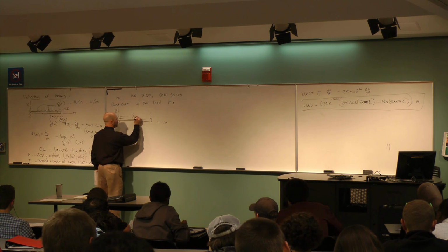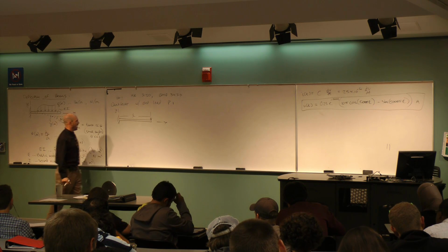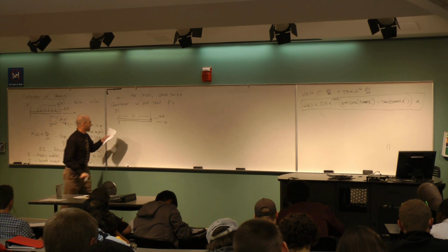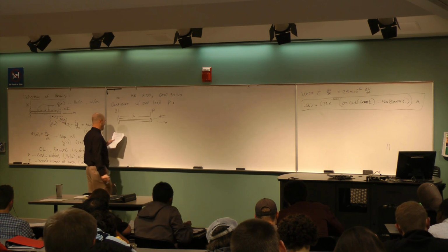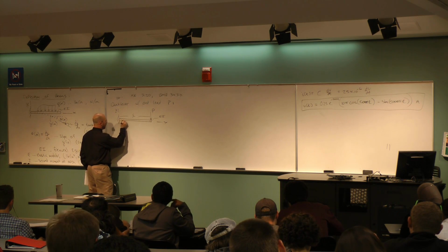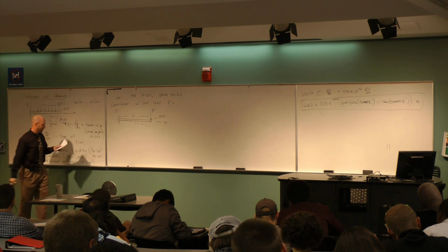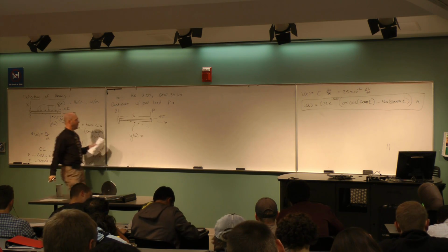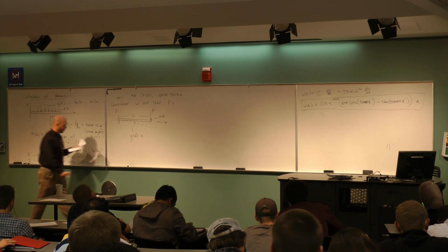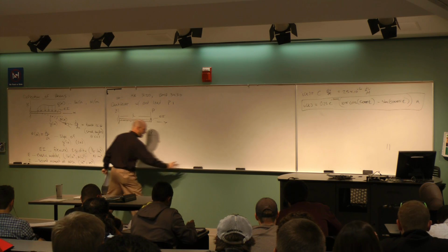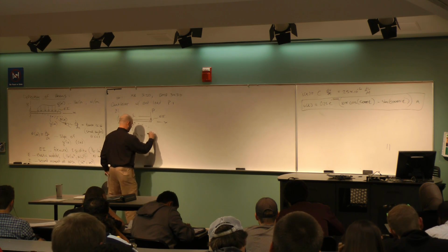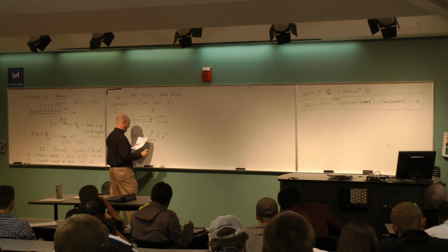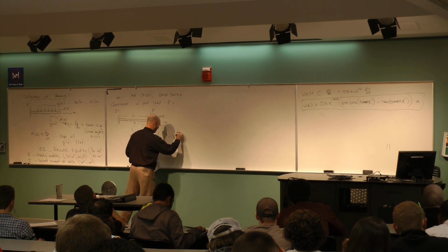The length of the beam, L, is one parameter. And the beam has property EI associated with it. And this is a load P over here at the end. The beam is going to deform in some way like this. So this is the equation of the deflection curve, y of x. It turns out, in strength of materials, you can solve for this deflection curve, and the answer is the following: P divided by 6EI, times a polynomial, x cubed minus 3L x squared.